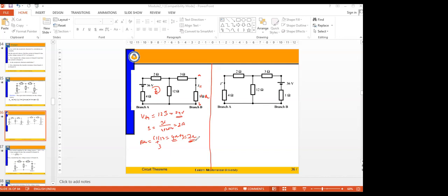Do you have any doubt with that? No, sir. So this is a resistance, this is a voltage source, and what is the RL value? 1 ohm, right? So this is 7 ohms, and this is 24 volts. So what's the value of IL going to be? I write it as I1. I1 is equal to 24 by 8, that's 3 amps.